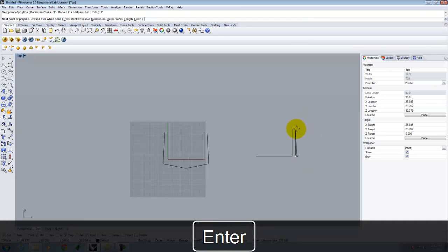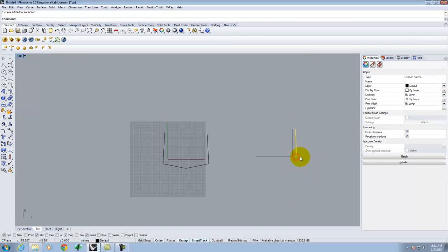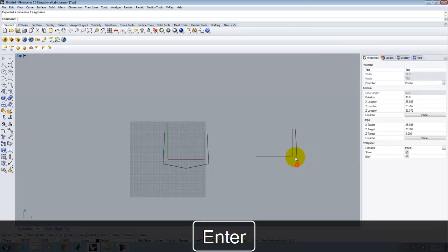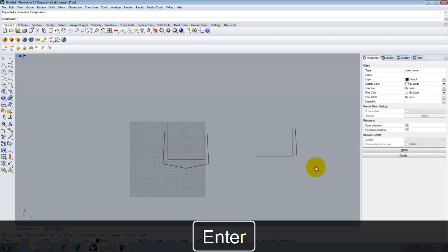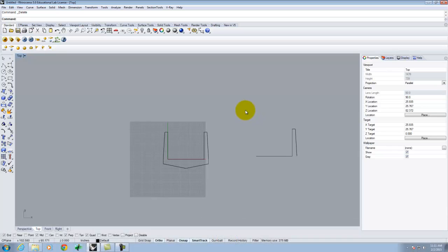right? And then I could come back up, and I could make that little shape, and then I could go back in and delete these extra pieces. There's delete, and then I could explode this one, and then I could get rid of that one. But to me, that's a whole lot of extra work that's not necessary. So if you get used to using those relative coordinates at certain moments in time, and you think about the basic grid system, it's far more efficient.